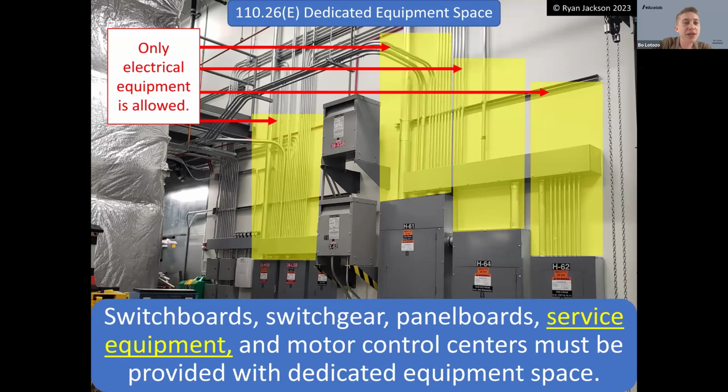All right. What are some examples of 2-inch thick concrete or equivalent in Table 300.5 minimum cover requirements? Okay, yeah, that's interesting. So 2 inches thick of concrete or equivalent in Table 300.5(A). I'm trying to recall exactly how that phrase is used, because 300.5(A) is how deep you have to bury underground wiring, right? So if it's in a trench below 2 inches thick concrete or equivalent, I mean, personally, and this is just me talking, I would consider asphalt to be equivalent,